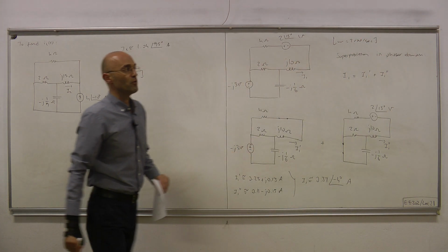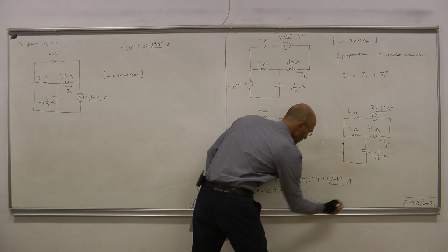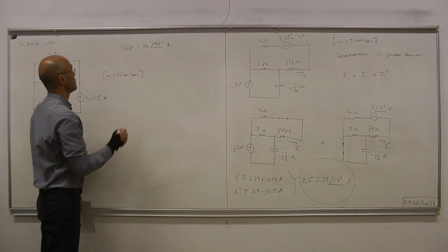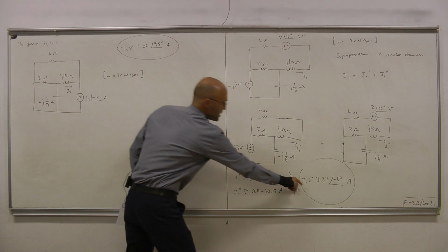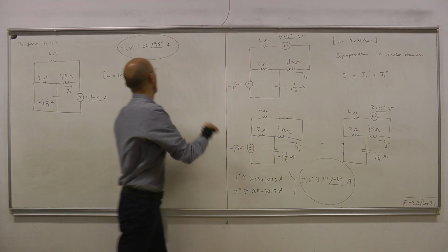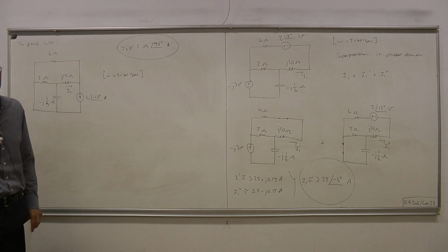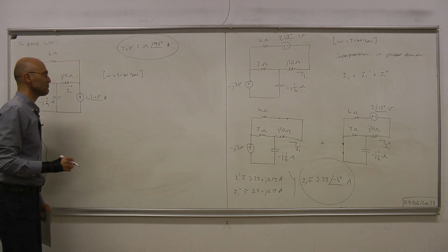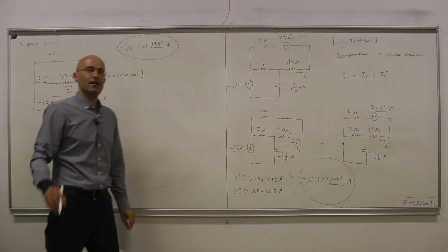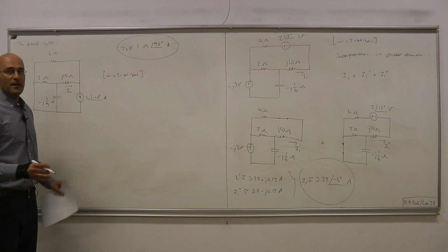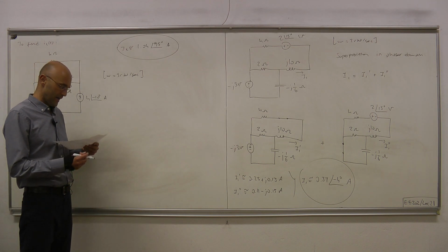And now with this piece of information plus the phasors that we have obtained, we can figure out I1 of t for that frequency, I2 of t for that frequency, and then combine those two time domain signals to obtain I of t, which is the current that we measure through the inductor when all the sources are active.